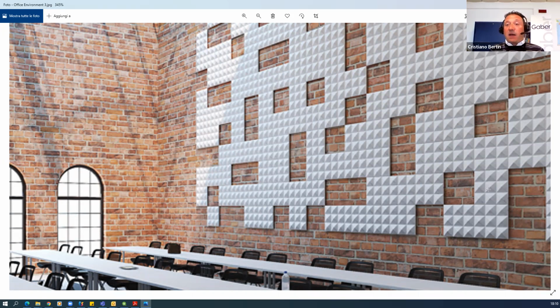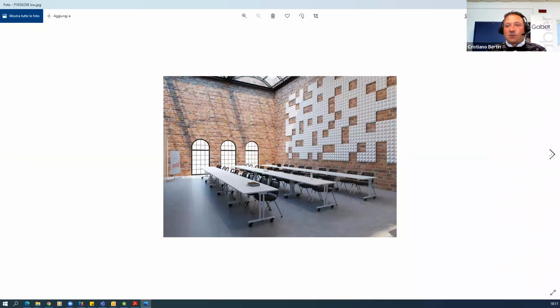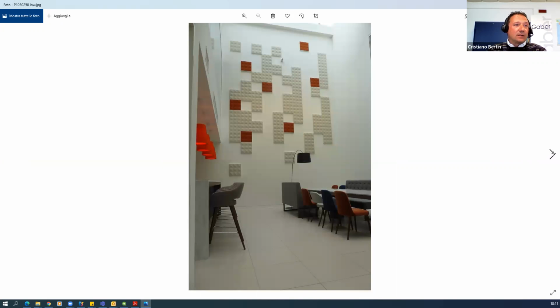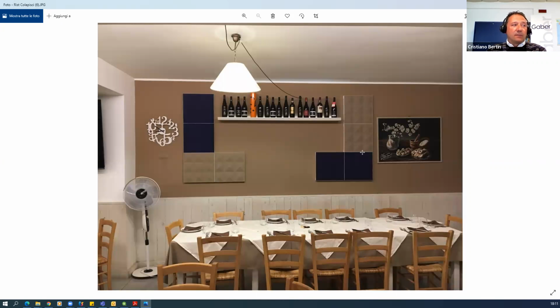So it's better to fix it over the floor, at least 40 centimeters. And better as well is having the possibility to fix it at the height of when I'm standing up, 1.50 meters, 1.70 meters, where normally the source of the noise comes from. Okay. So these are just small secrets on how to fix that.